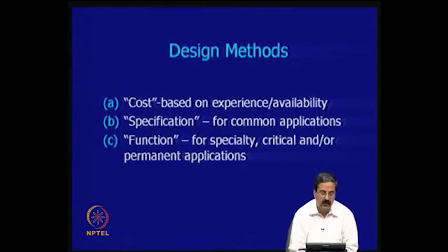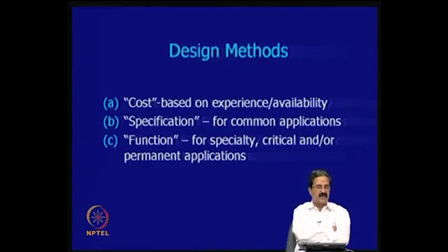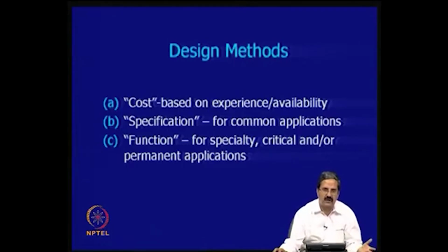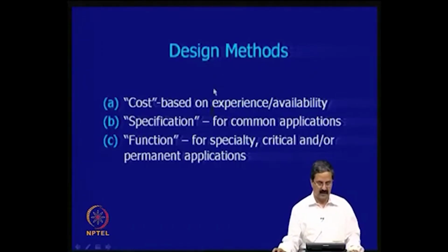Then the second way of implementing these techniques is that there are some specifications, for most of the common applications, like in landfills. In Government of India, there are some minimum standard guidelines and specifications you have to follow, like this should be the thickness of the clay liner for the municipality, this should be the thickness of the geomembrane for that area, that is it. And if there is a waterlogged area, this is the specification you have to follow, whether it is IRC or landfills and all that; they have specifications that one should follow properly. So, in a way, the design methods are the methods that help you to implement.